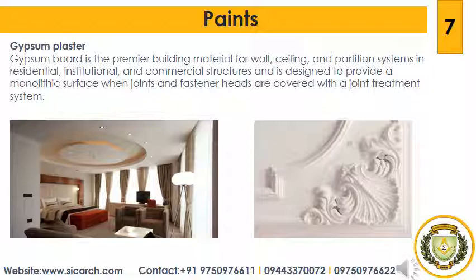It is practically not affected by bacteria. It is slightly soluble in water, about 2 gram per liter. Hence, it cannot be adopted for damp conditions and external work. The bags containing gypsum plaster should therefore be stored in a dry place.